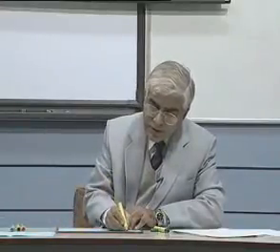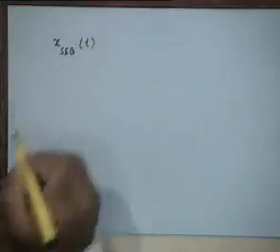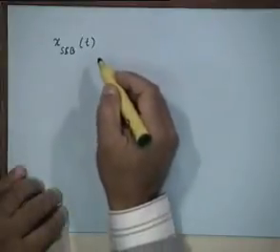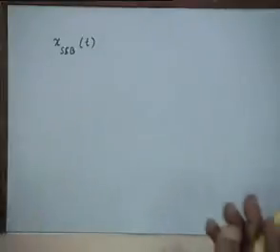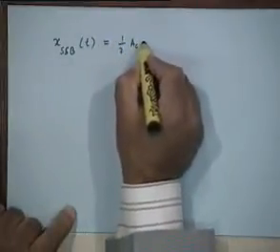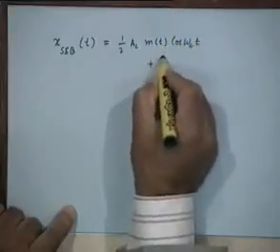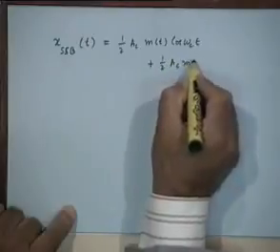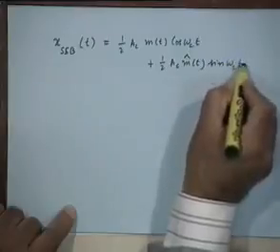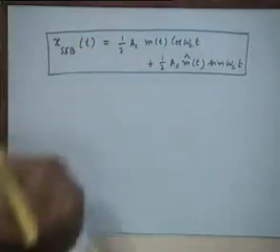So that gives me a closed form mathematical expression for the SSB signal, the single sideband signal, in terms of the message and the carrier, just like we had for the DSB-SC signal, and that is equal to half AC mt cosine omega ct plus half AC m hat t sine omega ct, right? A very neat and interesting expression.